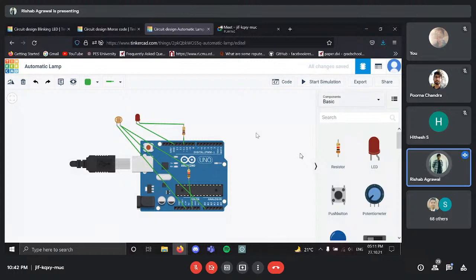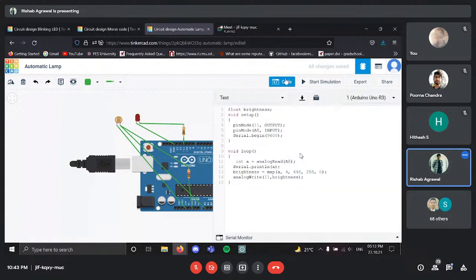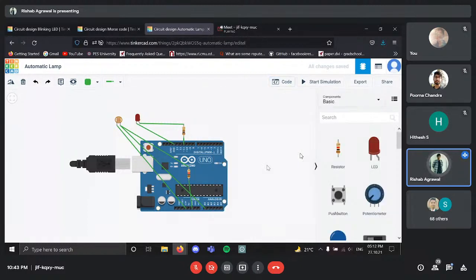No, you can actually declare the brightness variable inside void setup as well, and yeah, it would be preferable to declare it either outside or inside void setup, but inside void loop would not be nice, because if you declare it again and again as void loop runs again and again, it would probably slow down the code. And also, let's just check. Yeah, it's better if you declare it beforehand, because it allows for faster execution, but it shouldn't really matter.